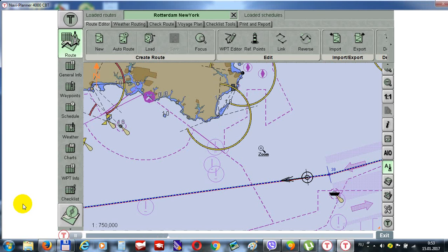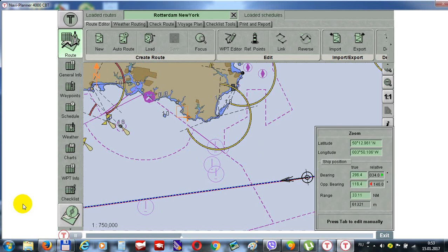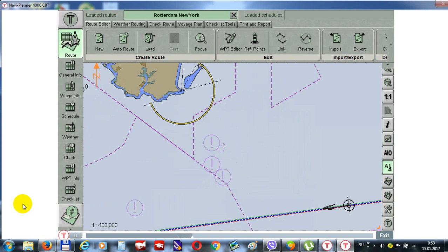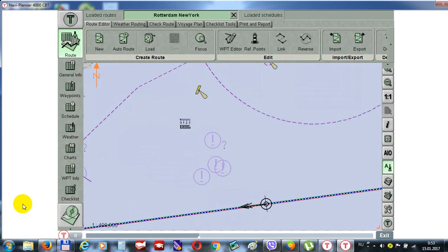Zoom cursor appears on the chart panel by pressing the right trackball button. Selecting the left trackball button turns on Zoom function. The cursor takes the form of the graphic cursor. Position the graphic cursor in the corner of the chart fragment. Select the required chart fragment by moving the cursor. Press the left trackball button. The chart panel scale will change so that the selected chart fragment is fully displayed on the chart panel.